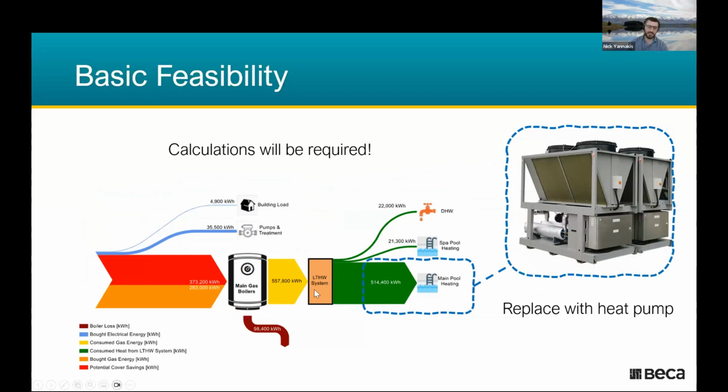And the big thing is you just don't want to take out a boiler and replace it with a heat pump. You want to calculate how big that heat pump is. Traditionally, gas boilers were oversized because they were cheap in capital costs, whereas heat pumps are not. So that's why you want to do it, for capital cost savings and understanding that.